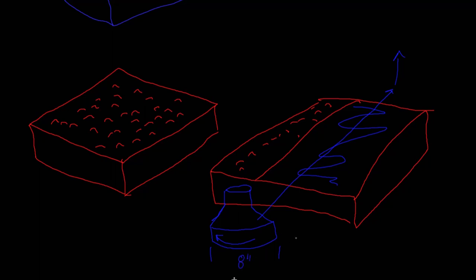They go as far down as 2 inches. If they go below 2 inches, they may be called an end mill, like a carbide insert end mill. So yeah, that is the main function of a face mill.